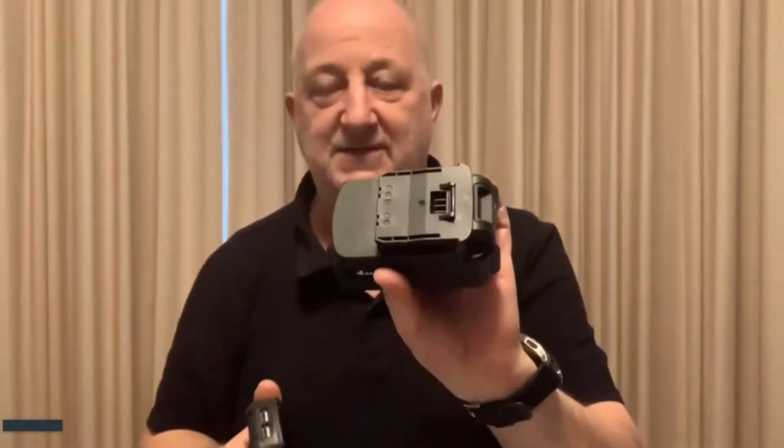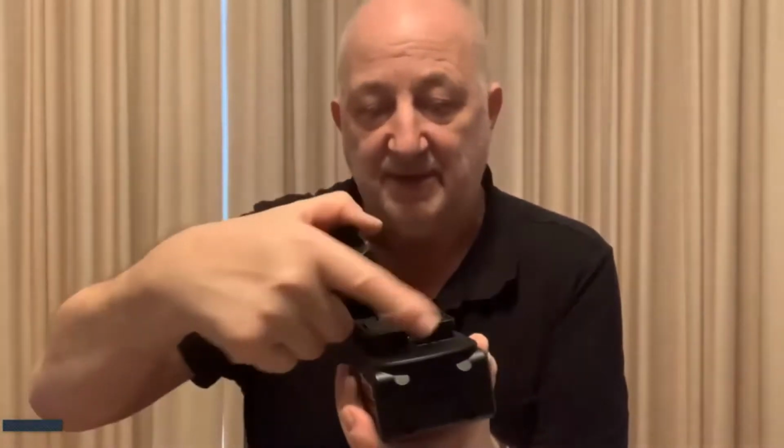And I frequently power the whole thing off this. This is great. This is an Aldi battery and an adapter that I got with an Aldi kit, which has USBs. This unfortunately is only 2 amp output, and that's not enough. So my next step is going to be building out from here with a couple of spade lugs, and I'll go and get a 3 amp voltage converter, so like 20 volts down to 5 volts. Probably I'll get that from Banggood or from AliExpress because it's a way to do it.